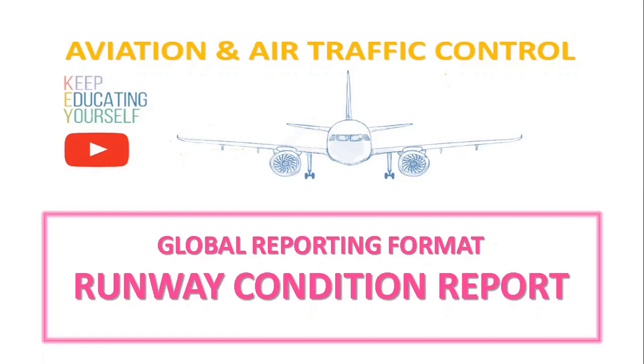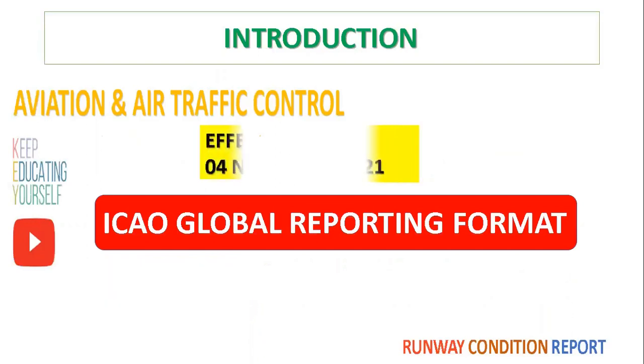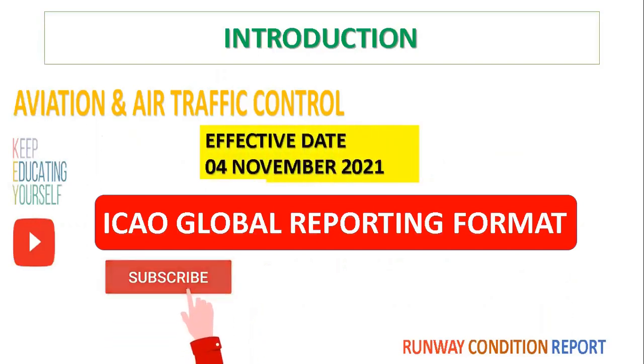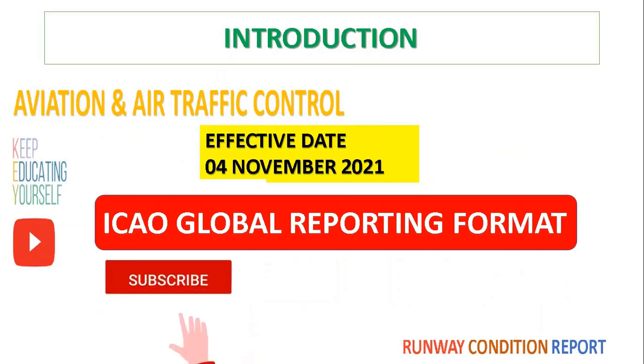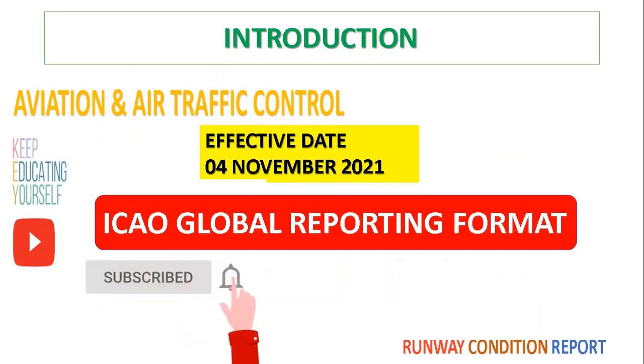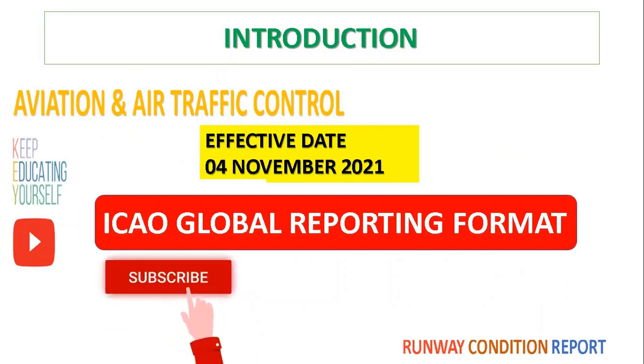So today, we will discuss the global reporting format on runway condition report. With effect from 4th of November 2021, aerodrome operators are required to assess and report runway surface condition through runway condition code. The reference of the same is given in PANS-Aerodromes, Doc 9981, Chapter 1.